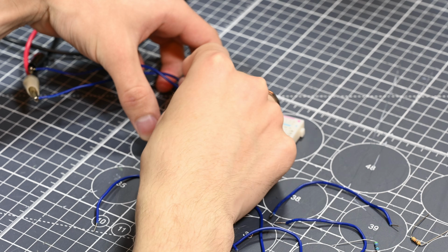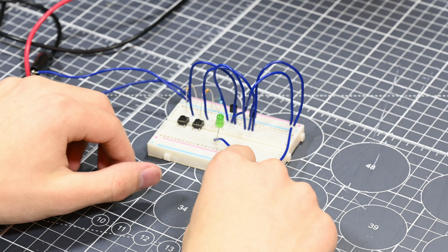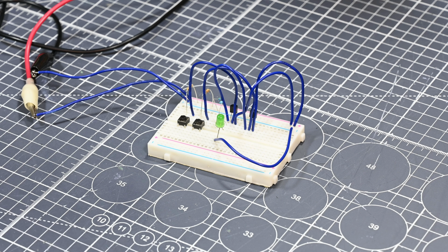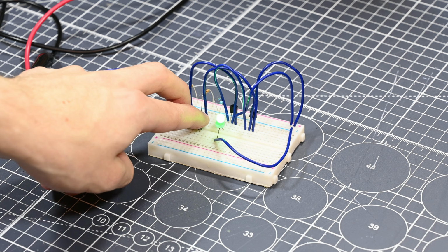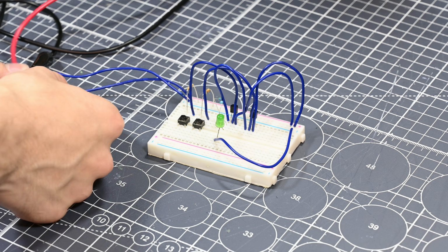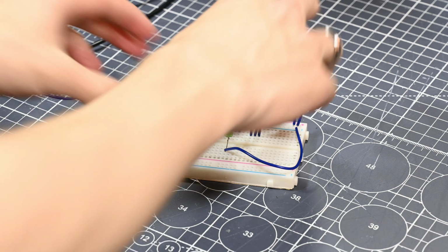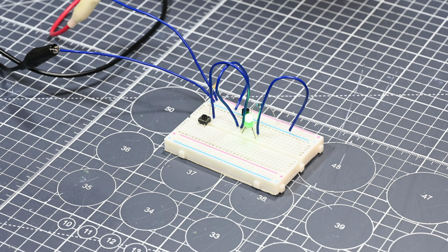Then, I reconfigured the 2 transistors to form a different kind of gate, an OR gate. The OR gate takes the 2 inputs and basically just passes them straight through to the output. So the only time that the output is off is when neither of the inputs are on. If one input or both inputs are on, then the output will also be on. The only reason that this is different than 2 wires that get conjoined into one is because this gate doesn't let the inputs feed back into each other, so if one input is high, the other input doesn't get pulled high too.